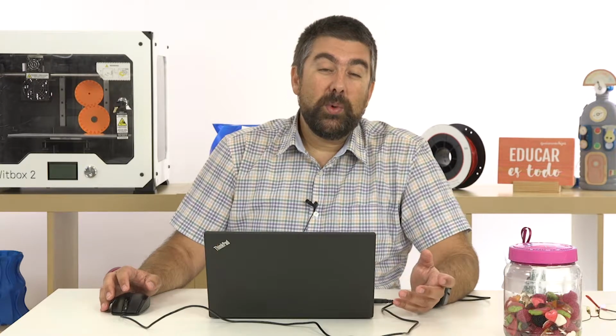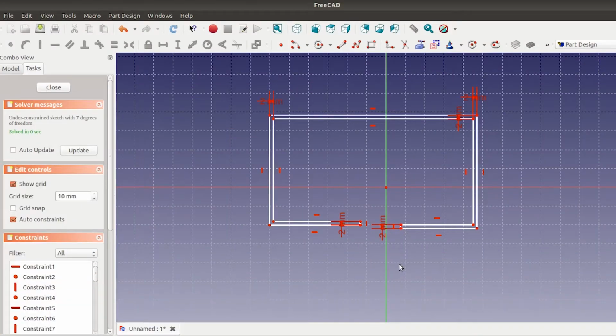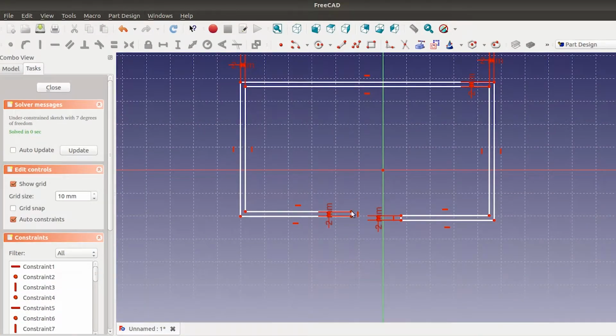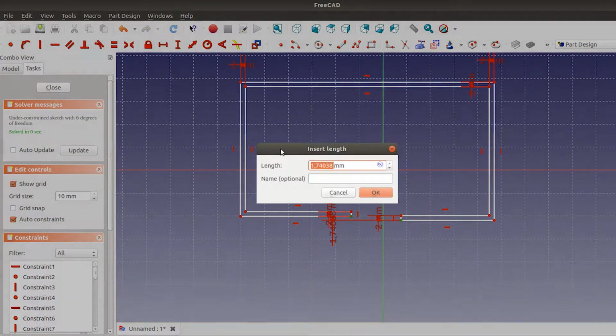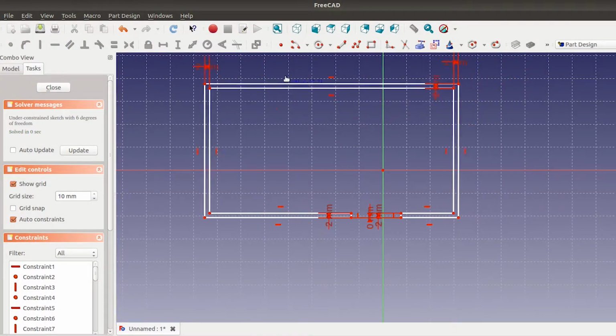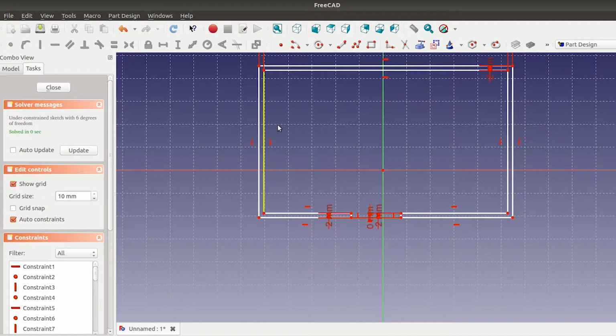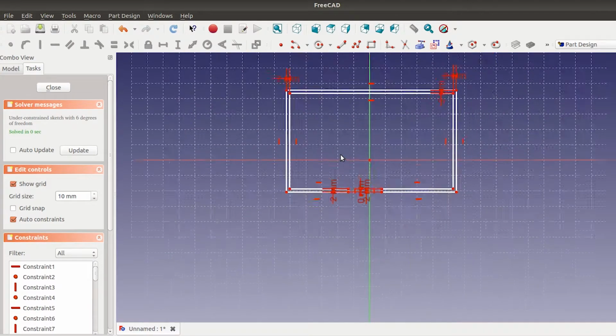Remember, this width is up to you. Maybe in the maps we are used to working with for blind people, it is 2 millimeters, but if for any reason we want to make it bigger, 3D printing allows us to make it as big as we want. Just decide which is better for the purpose you are working on. So once we have this, and we can see it here, we can make this point and this point be at the same height. For that, the distance must be 0 millimeters. So we have already our plan, okay? If we want any other dimension, we could just put it there. Just leave it like this right now.